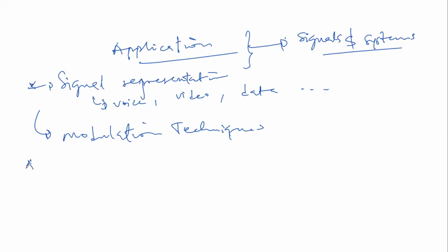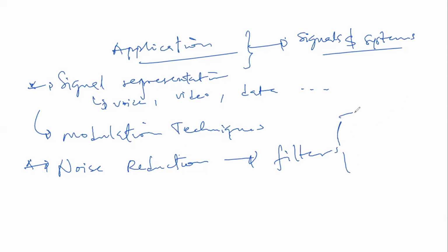Now, one thing we try to deal with, those of you that do machine learning, that do artificial intelligence, and a whole lot, is noise. We want to do noise reduction, right? So it all rises and falls on the discipline and principles of signals and systems. Because here we want to figure out how to design filters. Now, we mentioned in our lecture, these filters could be low pass, they could be high pass, they could be band pass, even band stop filters, okay?